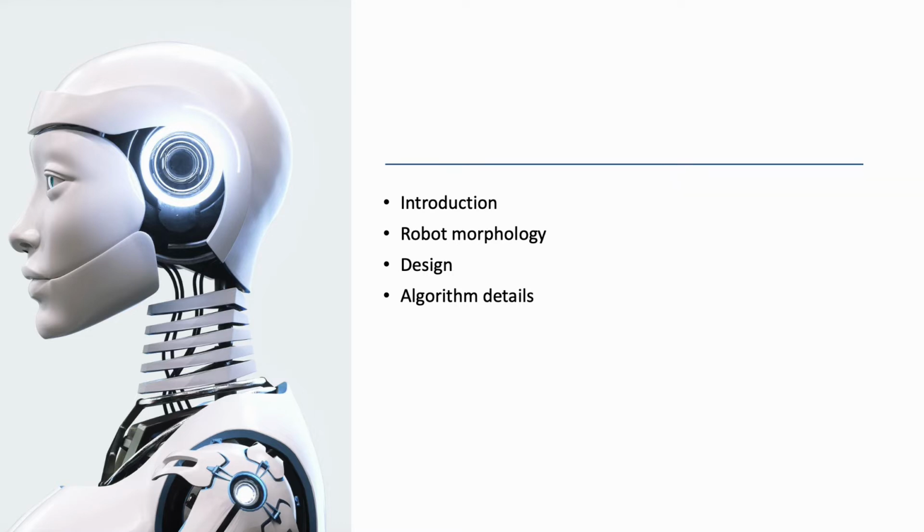And then followed by the algorithm. Initially it computes the inverse dynamics, and then the inverse dynamics gradient with respect to inputs from all the links, and finally it calculates the forward dynamics gradient by multiplication with the inverse of the mass matrix.